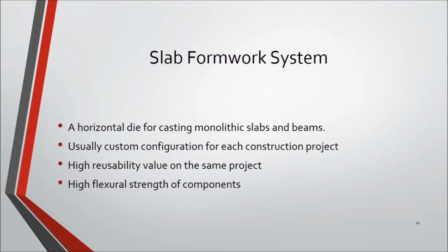Slab formwork systems act as a horizontal die for casting monolithic slabs and beams. Since the floor plan for each project is different, these are often custom-made for each construction project. If the designer designs the project appropriately, then the same slab forms can be reused again and again with very little adjustments. Let's see the current trends in slab formwork systems.